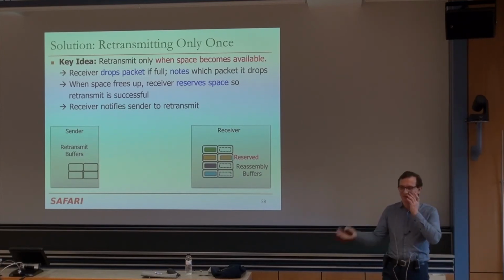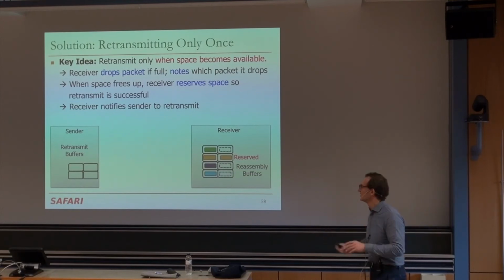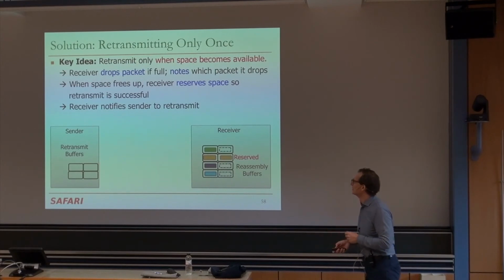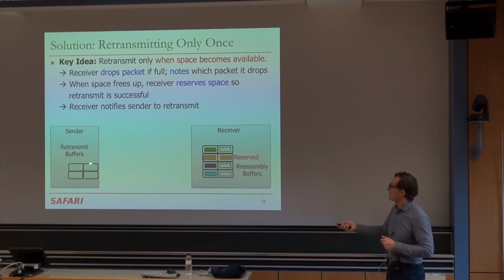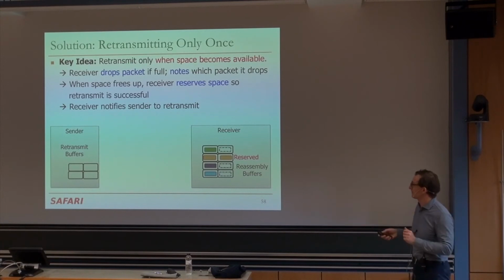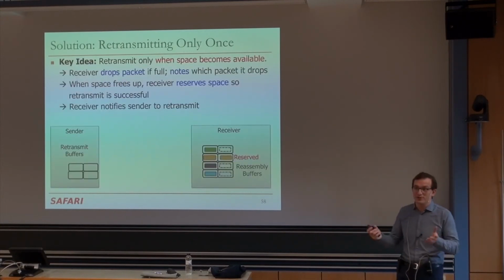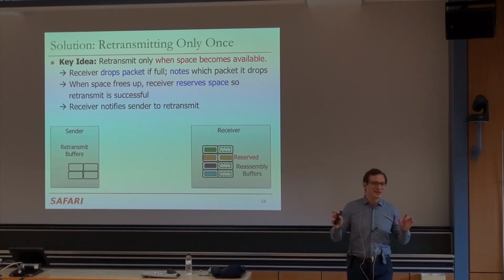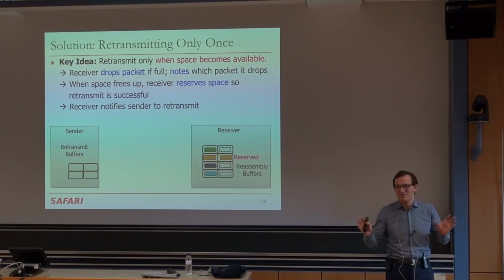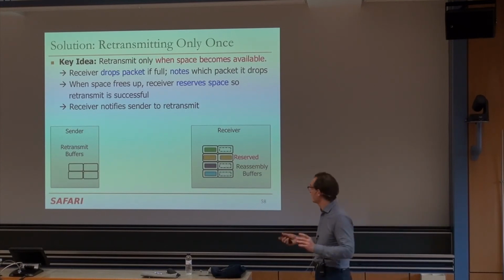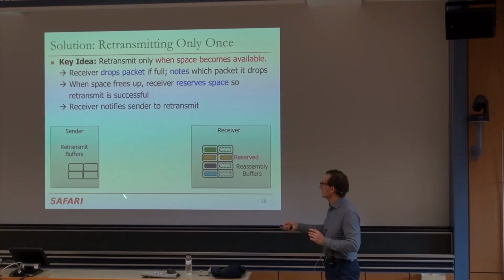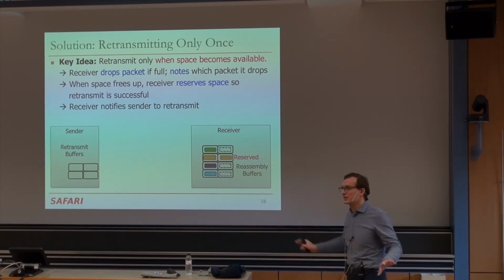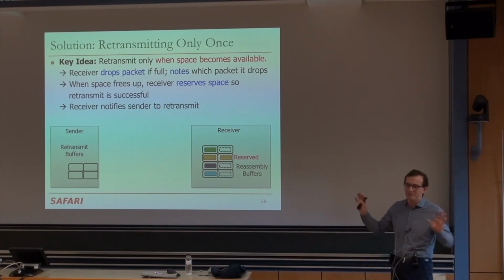So it gets the best of optimistic and pessimistic protocols, except there are of course still trade-offs. It's somewhere in the middle. But at least it doesn't have the delay initially, and it doesn't have a lot of retransmits. Okay, so that's one example protocol that you need to handle. So basically, in the end, you cannot get rid of buffering because you have to put these packets somewhere. The question is, where do you do the buffering? And here the buffering is actually only in the edge nodes, senders and receivers. Internally, the network doesn't have buffers, except for pipeline latches, of course.